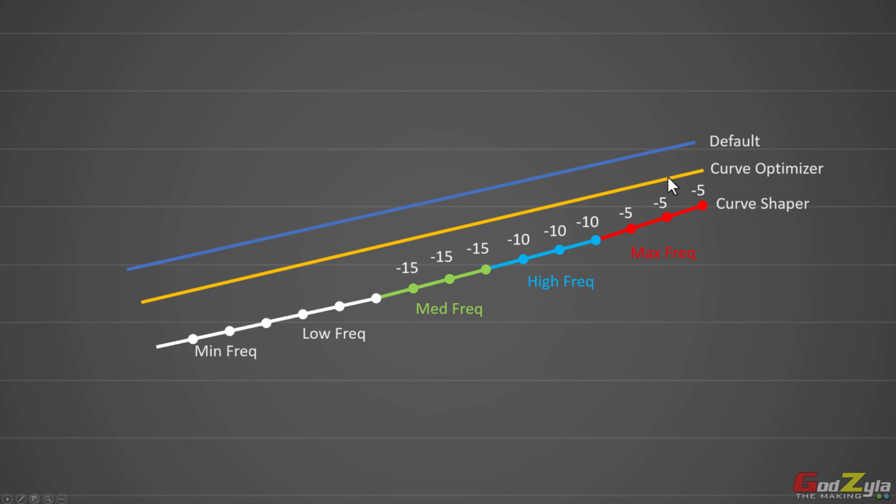Having set curve optimizer to -20, you're pulling the current lower. Imagine this is actually running at around 200 watts or so, or at that amperage. When you do your curve optimizer, it's going to draw down. Instead of pulling 200 watts, it's pulling much lower, maybe around 160 or so.